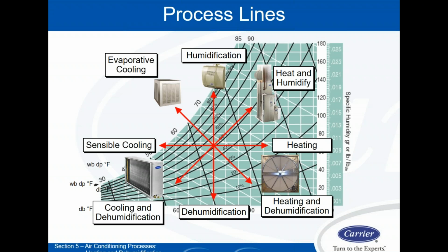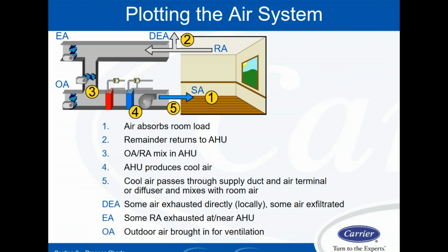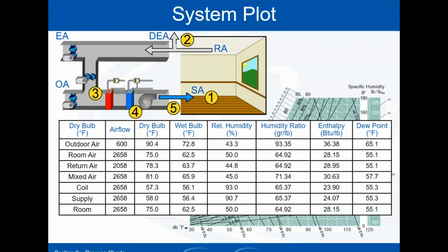In the system, Philip asks, in the plot system, do you consider filter pressure drop significant? Only one filter needed, or multiple, or in multiple locations? The filter itself is going to have no effect on this process here, because the filter is going to clean the air, which is fantastic. No effect on this discussion. And it's going to have a pressure drop associated with it, which is already factored into the CFMs that I'm dealing with. And in this particular case, this fan is running whatever CFM it has to run at to overcome all of the static resistance of the entire system.